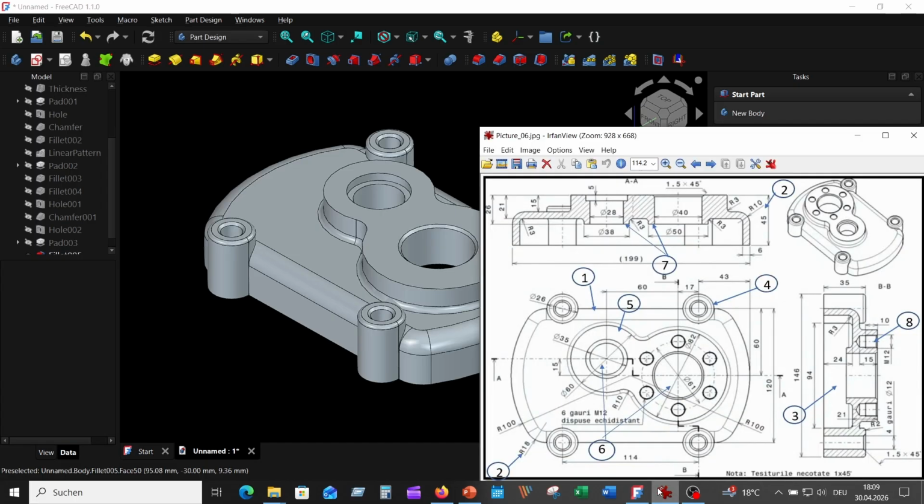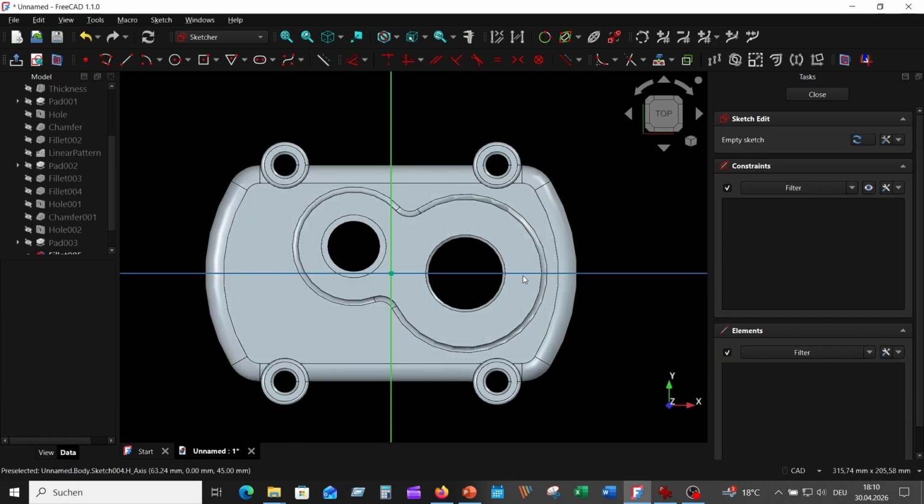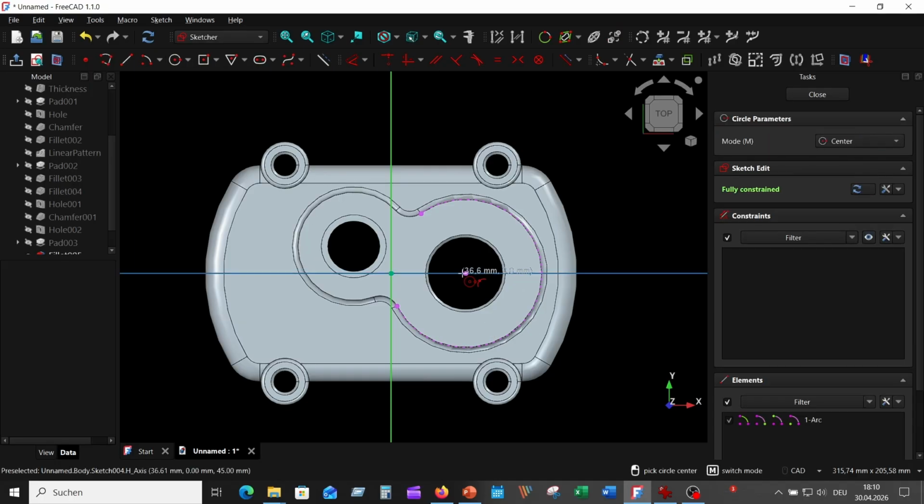The last step is to create the 6 holes with the threads. First, we create one hole and then we create the other holes with the help of the Polar Pattern tool. Select the top surface and then activate the Sketch tool. Next, extract the reference curve to define the center point. Sketch a circle with a diameter of 61 mm and then convert it to construction line.